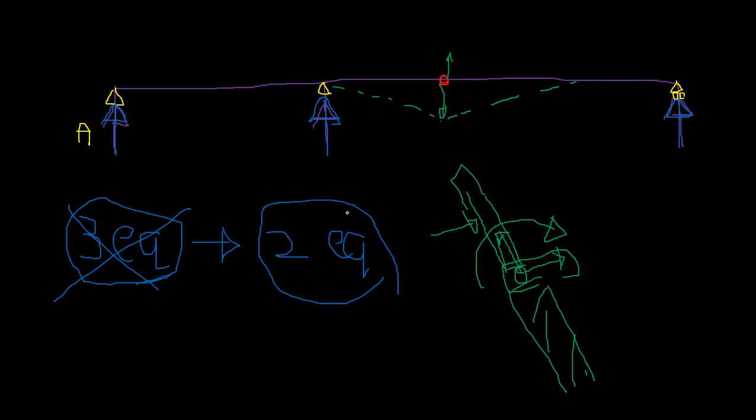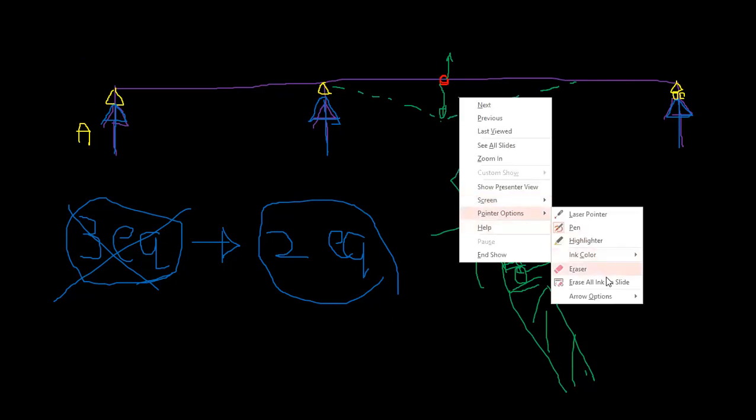So that means if it is allowed to rotate, what will be the bending moment? 0 at a hinge. So we know the value of the bending moment is 0. That means there's an additional equation we can generate, right? So that means it is going to become determinate, right? There's a hinge.